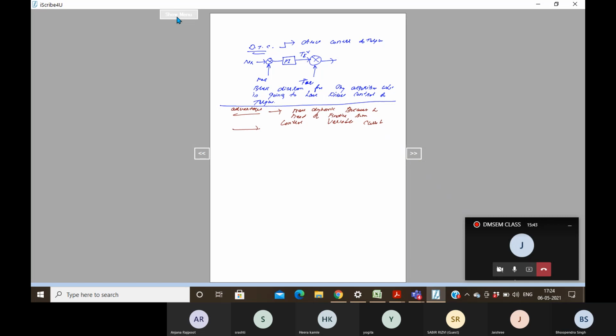Then, as in field oriented control, you have to implement ABC to DQ transformation and again back DQ to ABC. So this coordinate transformation requires the rotor angle theta. So this made it very complicated. Your control algorithm was very complicated, right?